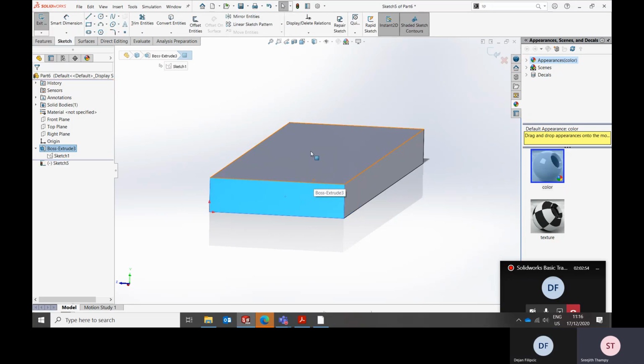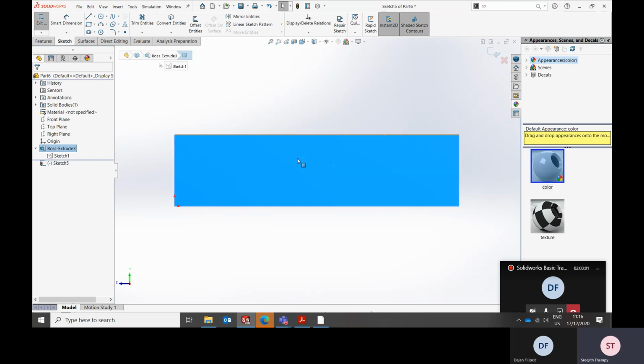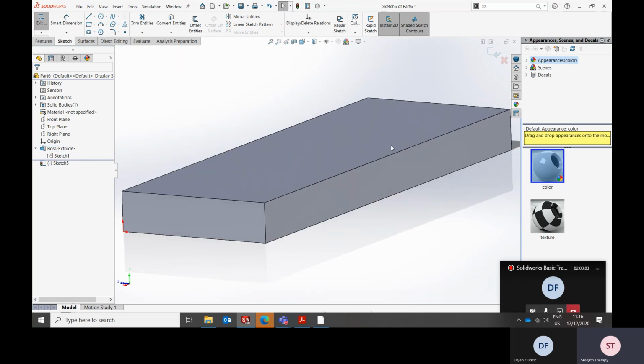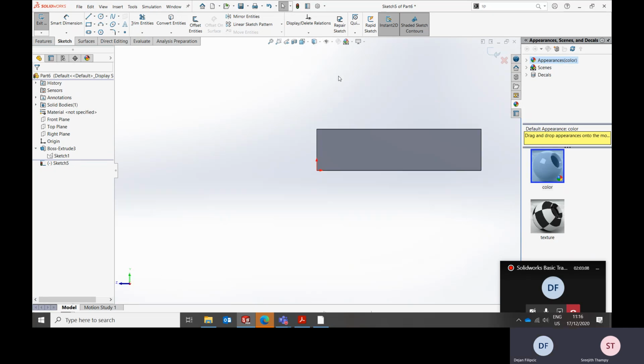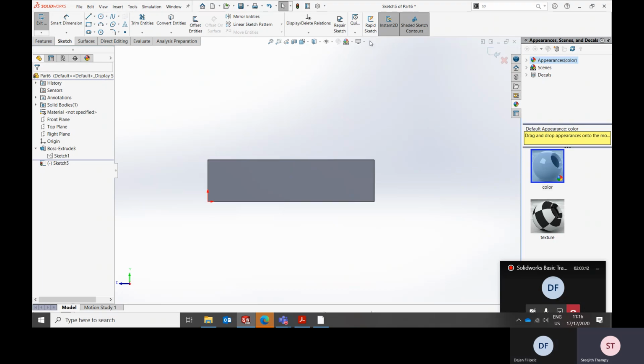Okay. Plus sketch. It is not automatically aligned normal to the screen, so I'll press Control 8. Now it is aligned. There is another option to do that. You can go here and press this, and you can also keep it here as a shortcut. If you want, you can keep it outside as well. So now the view is aligned.